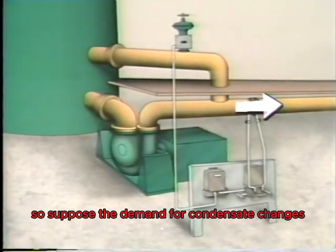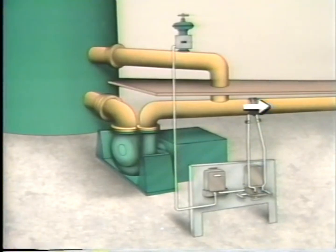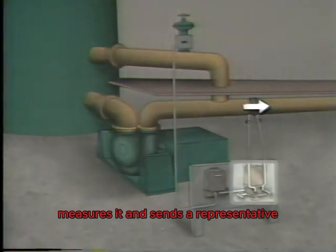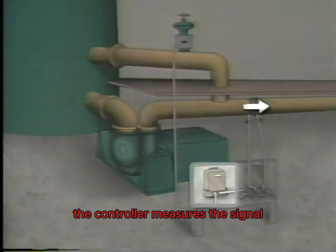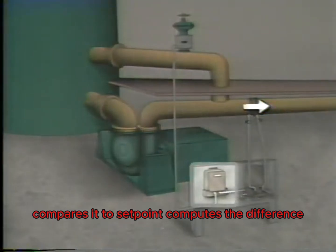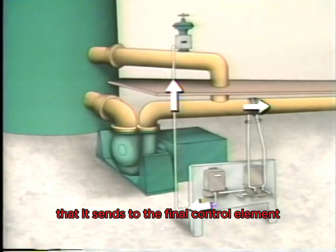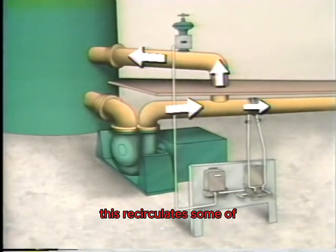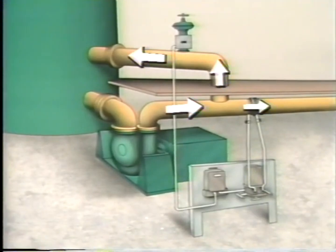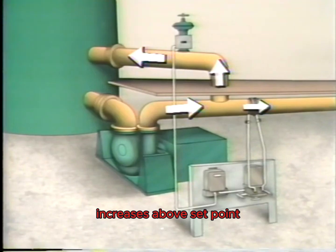So suppose the demand for condensate changes and the discharge flow drops below set point. The transmitter senses the change, measures it, and sends a representative pneumatic signal to the controller. The controller measures the signal, compares it to set point, computes the difference, and produces a corrective signal that it sends to the final control element. The final control element responds by opening the valve. This recirculates some of the condensate back to the tank to ensure that condensate flow through the pump increases above set point.